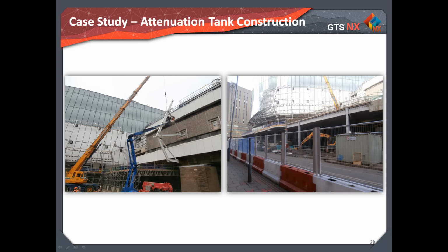Due to the construction program and the importance of installation of facade works on time, the sequence was to install the CFA piles, then the steelwork and deck to be constructed to provide the required access and platform for mobile cranes and spider cranes, and then the attenuation tank to be built underneath whilst the other construction activities progressed on the steelwork deck.